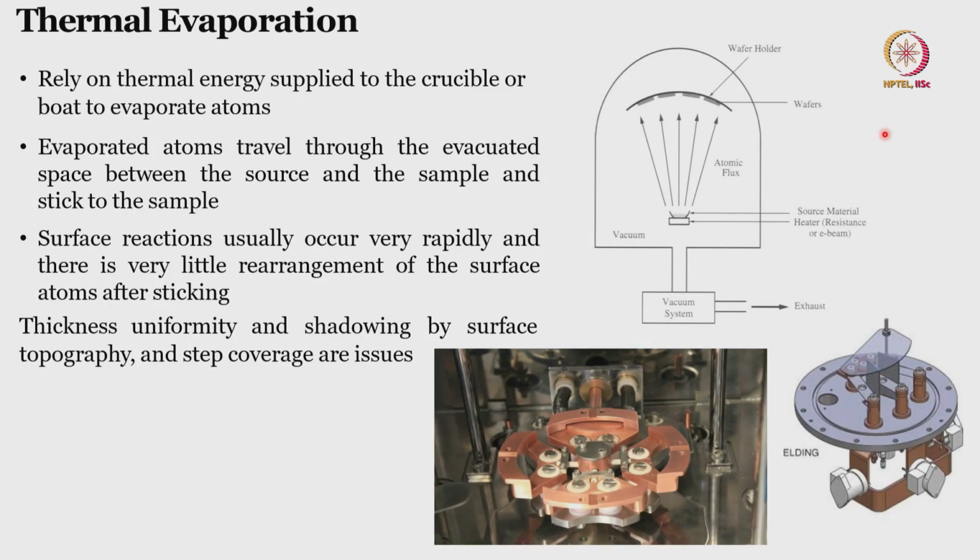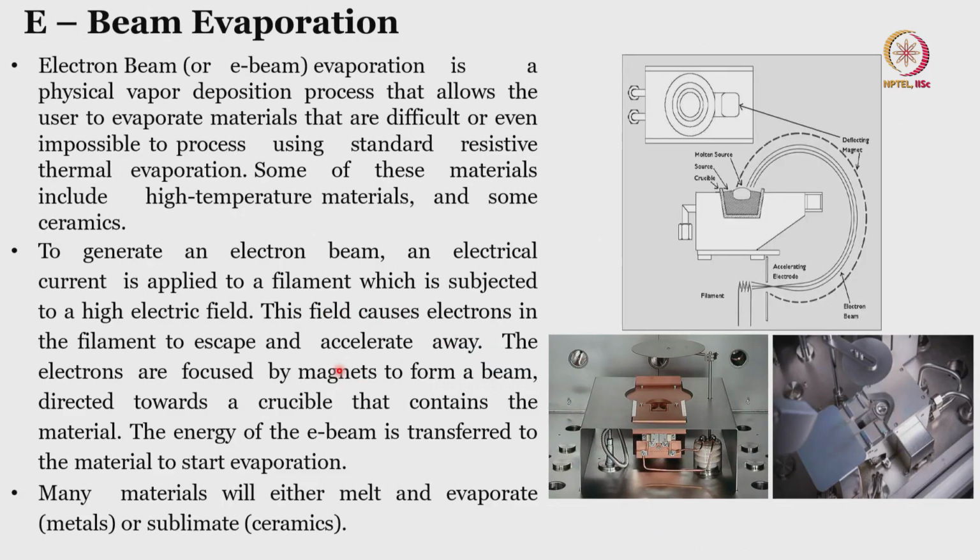How can you measure whether it is polycrystalline or amorphous? Using a technique called X-ray diffractogram. That is a material characterization technique. Thickness uniformity, and shadowing by surface topography and step coverage are the issues. So one can go for E-beam evaporation.